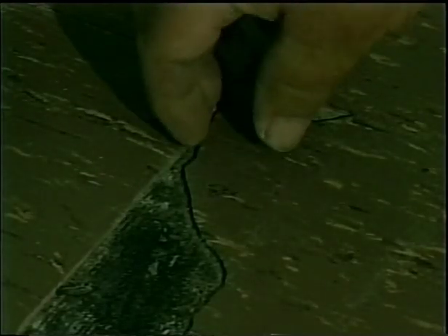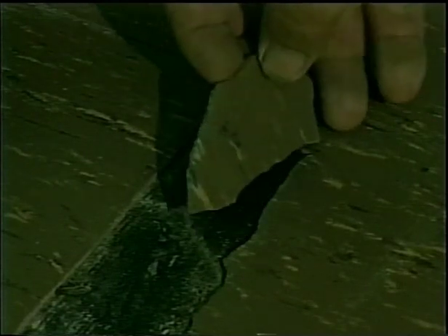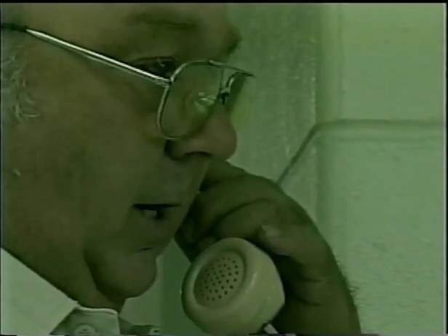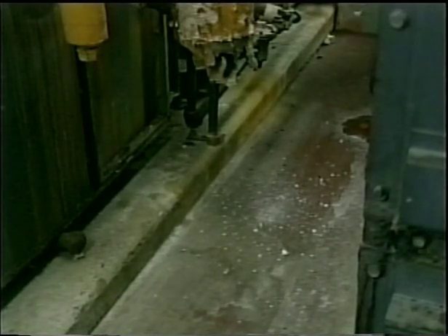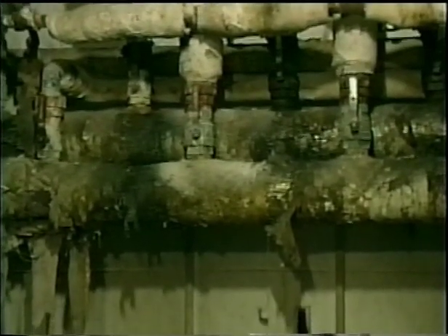Broken or damaged asbestos floor tiles must also be removed by asbestos abatement workers. Report any suspect broken tiles to the people in your facility in charge of your asbestos program. Spills. It is important to report any damaged asbestos-containing materials to the people in charge of your asbestos program immediately. If, for example, you discover that some asbestos pipe insulation has been knocked off a pipe, this would be considered a spill. As such, it would need to be cleaned up immediately by asbestos abatement workers.